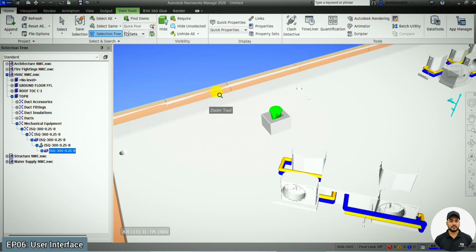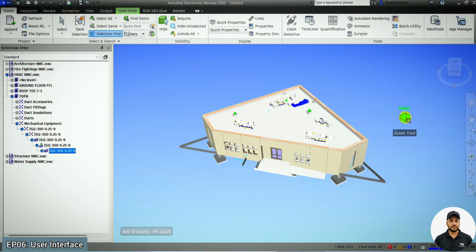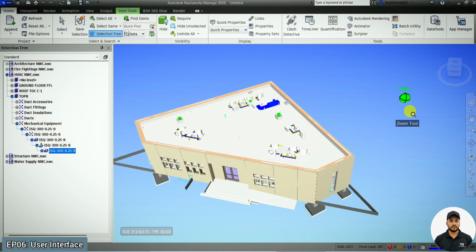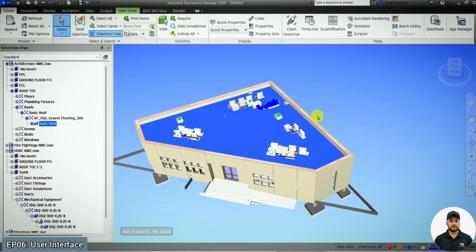So with the help of this, you can navigate your building and see your building as per your requirements. So these three are the most useful: pan, zoom and orbit tool. And for this Select, if you have used any one of them and you want to deactivate that particular navigation tool, you can simply click on Select. Otherwise you cannot select any element right now because the pan command is active. So to deactivate this, we use the Select option again. Now we can select our parts easily.